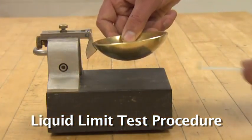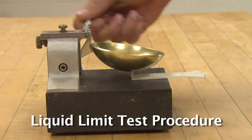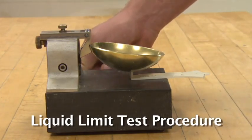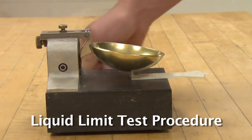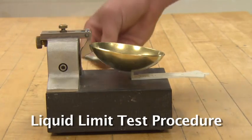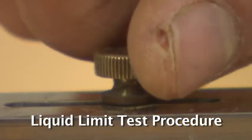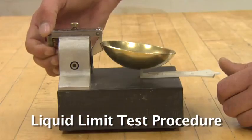Calibrate the apparatus by placing the grooving tool underneath the cup. Rotate the handle so that the cam just contacts the cup. If the apparatus is calibrated, the cam will just barely touch the cup and it will not lift it off the grooving tool. Loosen the set screw on the top and adjust the thumb screw in the back to raise or lower the cup.